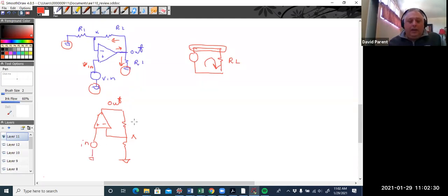Okay. And I'm going to use voltage division. First thing I'm going to do, though, is say I minus equals 0. Right? So this current, which we can call I minus, is another way to talk about it, right? It's 0.